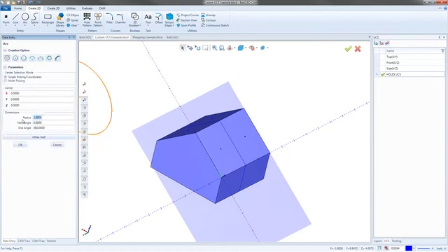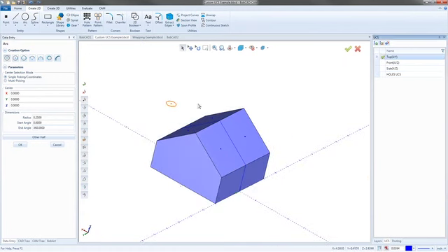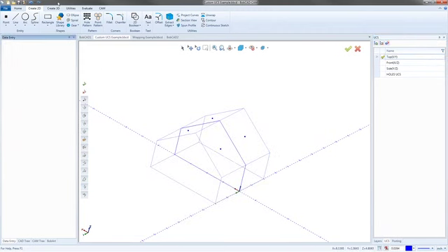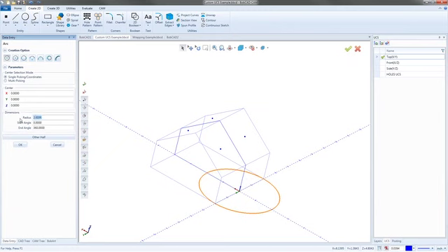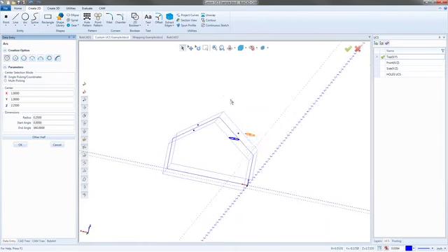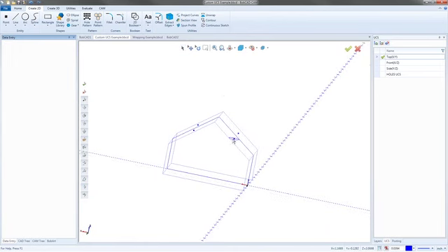So right here, I'm just going to change the radius to a 1/4 inch, and I'm going to slap some holes on here just to show the difference. Because we're in a top plane UCS, if I was to snap this arc right here, 0.25, and pick this arc or this point, if I wanted to extrude a cut through that with this arc, it's going to go straight down and through the part.